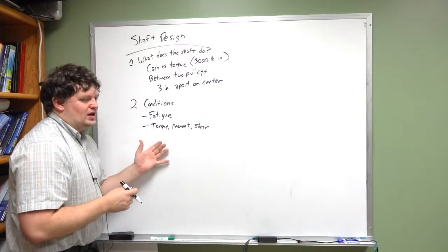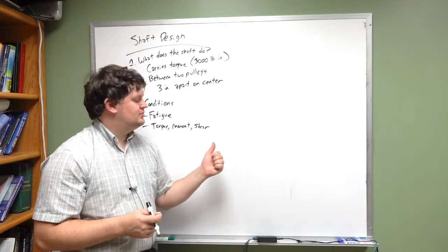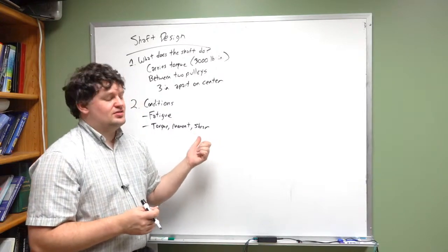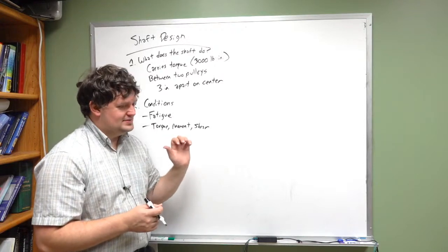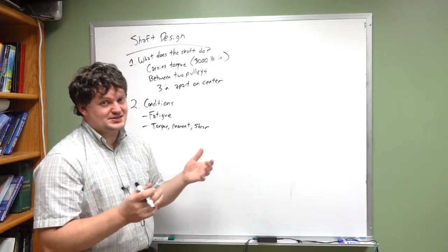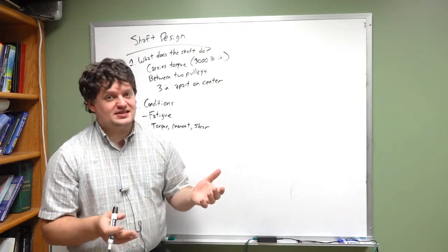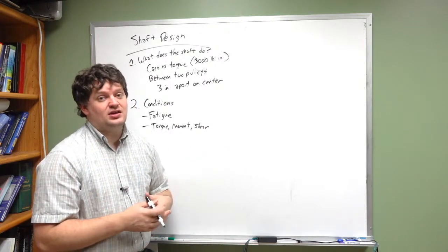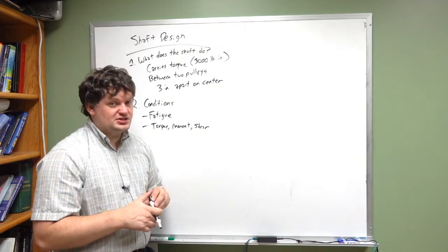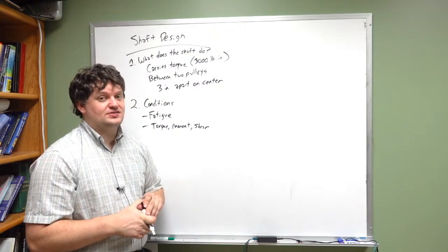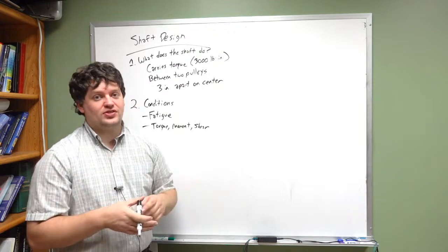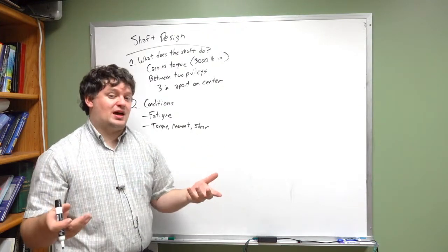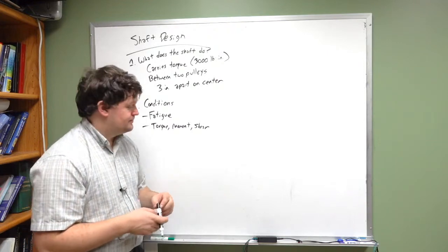But when you have the reading assignment, the book suggests that you don't design a brand new shaft. Use an existing shaft or redesign an existing shaft. Don't try to build something brand new, just because this process can be a little arduous. We have talked in this class a lot about stress analysis and fatigue analysis and all of those fun things. In practice, people don't really want to have to go through the math to figure that out. Okay?